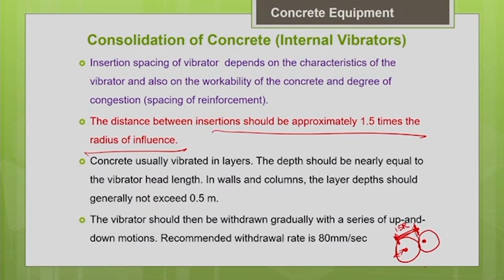Regarding the spacing between the vibrator insertions, it depends upon the characteristics of your vibrator, on its radius of action. If it has a better radius of action, accordingly you can vary the insertion spacing. It also depends upon the workability of the concrete.